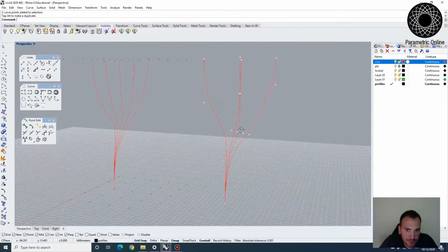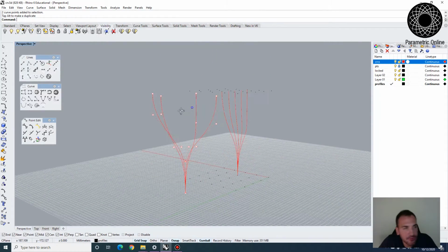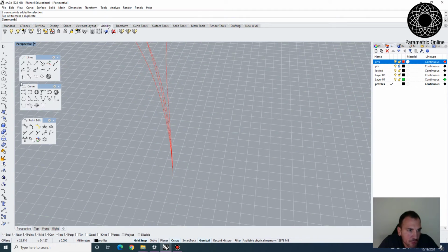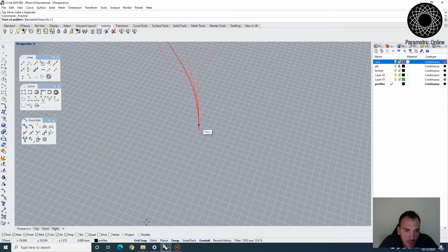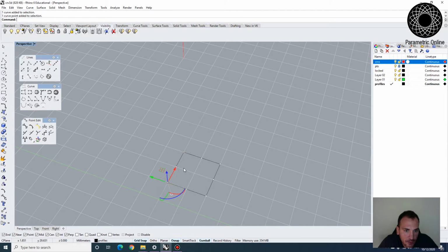Right, so it's kind of having a uniform shape at the bottom, and then it's going to have different profiles opening up towards the top. And I'm going to draw on the grid. So I turned my grid snap on. I'm going to draw like a quad shape. Basically, you can draw this type of polyline, and then I'm going to choose these points and do a scale.